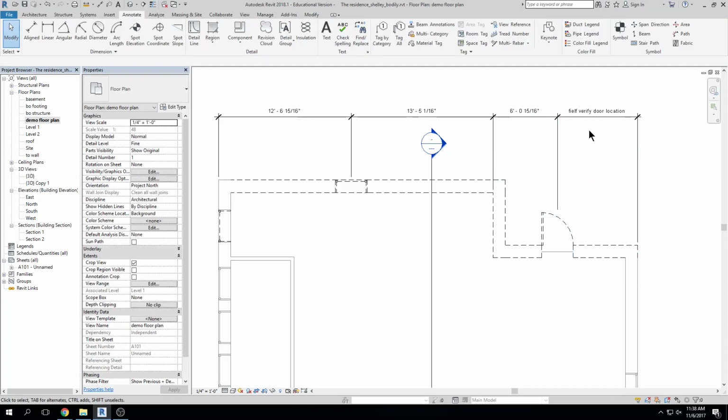When I first started using Revit, I constrained everything because I thought I don't want any of this stuff to move, right? But then I realized that things do continue to move in an architectural project all the time, right? We update them, we move things even by a half inch to make them line up. And so when you have a ton of constraints, I found that more than anything, I just got a million errors by constraining everything, right? So every now and again I do constrain something, but if I do constrain it, it's do or die. It's a very important constraint. I just don't lock things down in general because it causes more problems than it's worth, honestly.